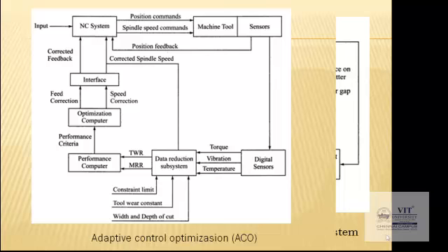If the speed is set to 3000, okay, for the particular operation, the speed required is only 2000, as calculated. What happens? By reducing the speed by means of override, the speed value automatically reduces. Okay, the program executes 3000 RPM, but the controller reduces the speed override from 100% to some percentage, so that 2000 RPM is obtained. So this optimized value is obtained.